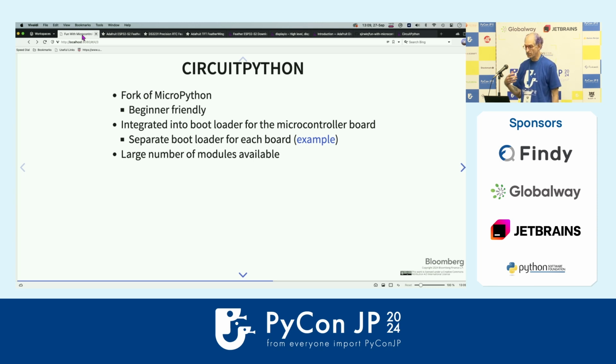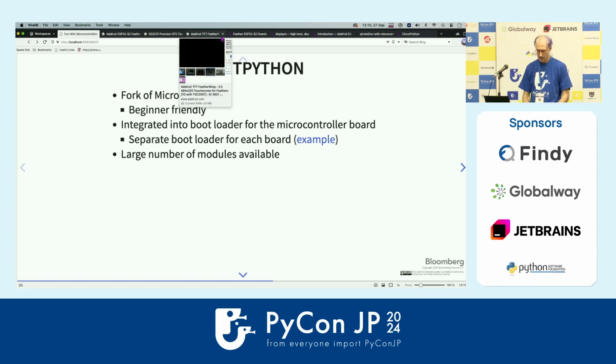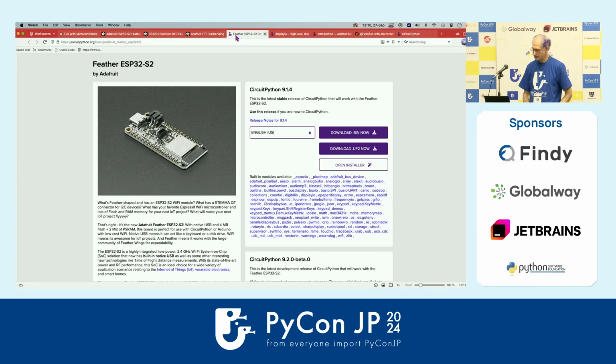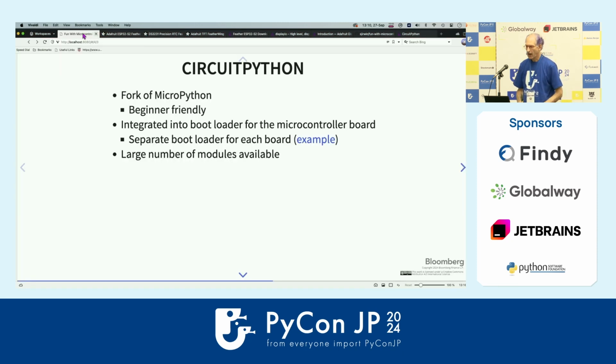CircuitPython is integrated into the bootloader for the microcontroller board. This is what boots the board up. Since every board has different hardware, there's a different boot controller for each device. Just to give you a sense, this is where I got the bootloader for the particular microcontroller that we used, and this is off of the circuitpython.org website. The other nice thing about CircuitPython is that it has a very active open source community, a lot of contributors, so there is a large number of modules available.